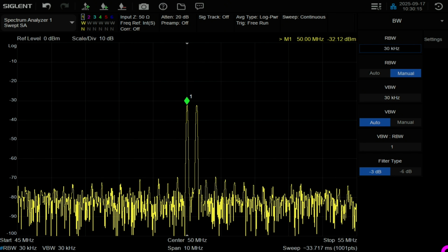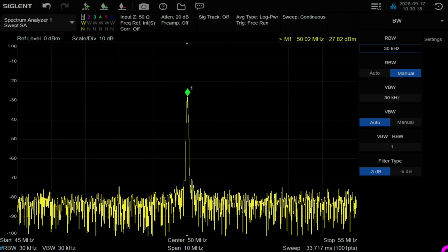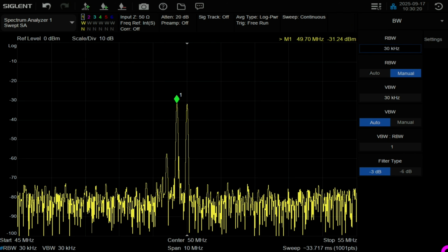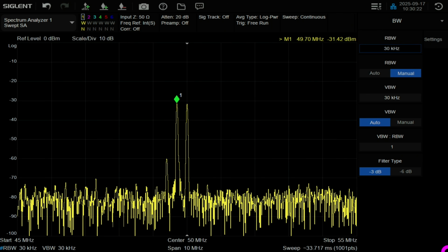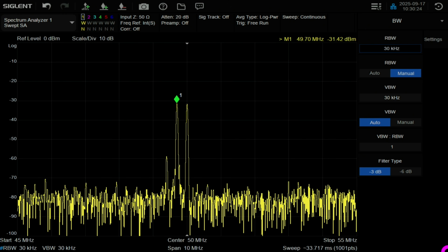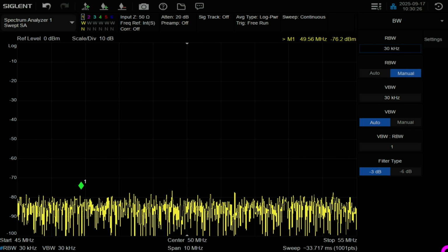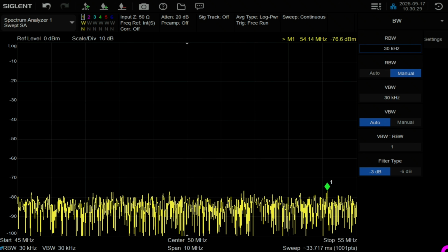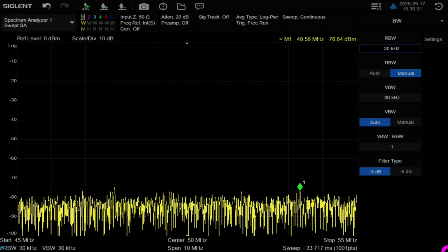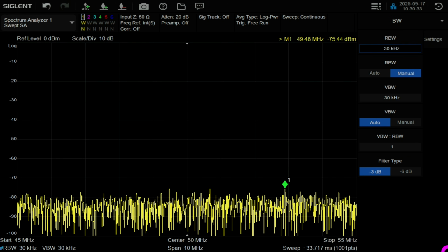All right, well, there's not much left. Everything else looks pretty good. Yeah, so, all right, well, the divider is working at 1.6, so that's not our problem. This really verifies the majority of that loop. So what else is left? Well, there's only a few things. The detector itself could potentially be a problem, and all the analog circuitry following that.